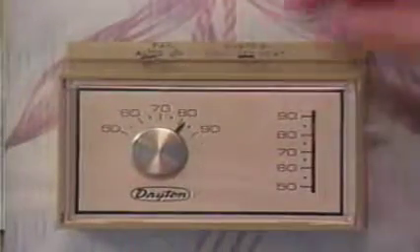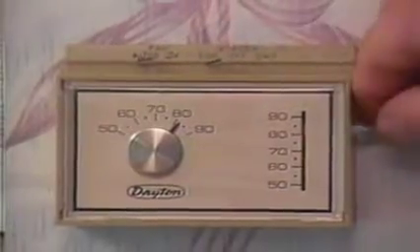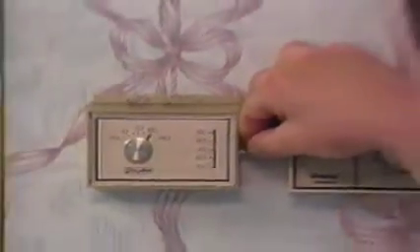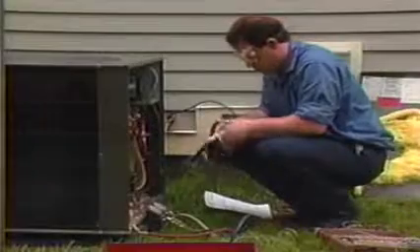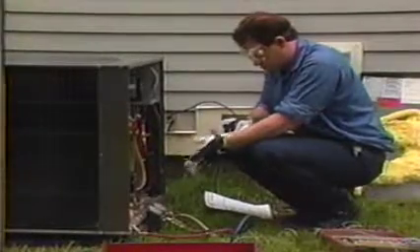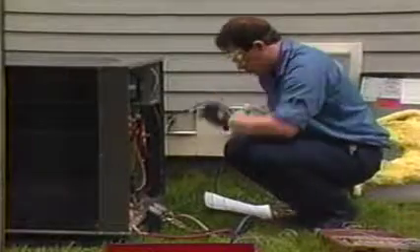Often, a technician can verify a power supply to the system by starting the indoor fan instead of using electrical test instruments. This quick check can save a trip under the house or up to the attic if the fan will start with the fan relay. Several things are apparent. The indoor fan is working. This means that there is control voltage and there is line voltage to the unit.